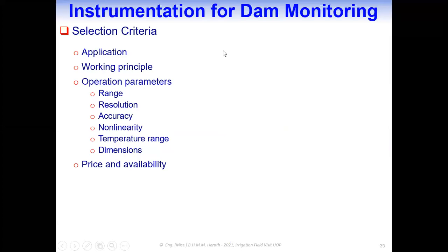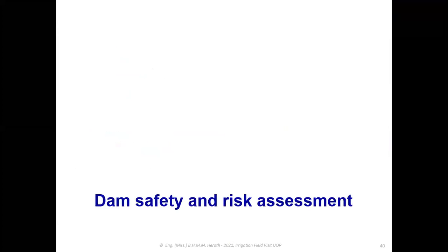So here, we should consider the application, its working principle, operating parameters such as range, resolution, accuracy, nonlinearity, temperature range, dimensions, and so on. In addition, price and availability are also checked.